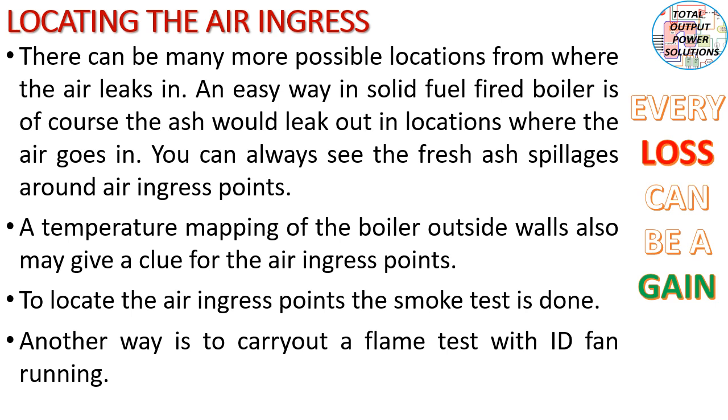Then, locating the air ingress. It is also a task to locate the air ingress, as there can be many possible locations from where the air leaks in. An easy way in a solid fuel fired boiler is that ash would leak out at locations where air goes inside. You can always see fresh ash spillages around the air ingress points.